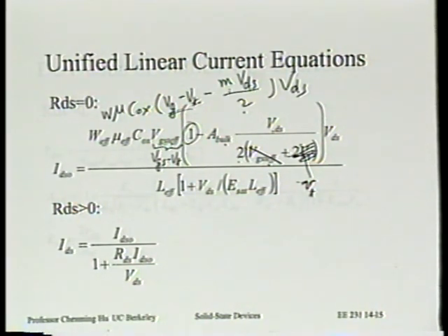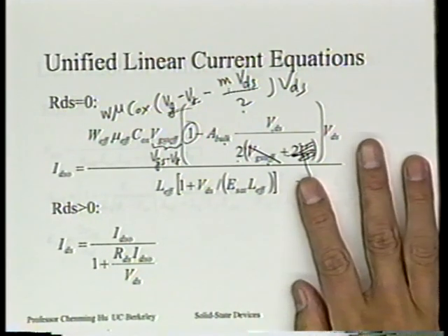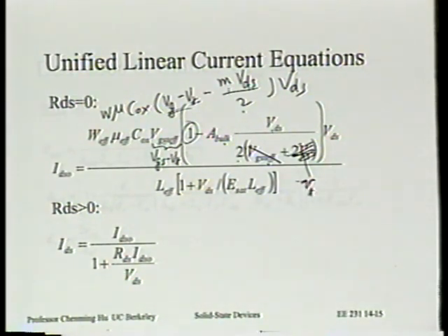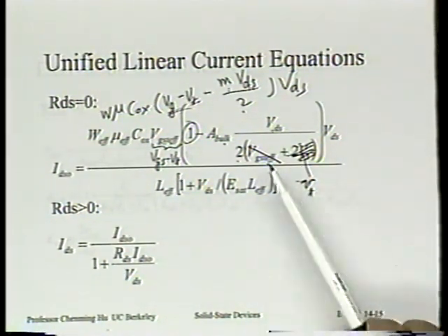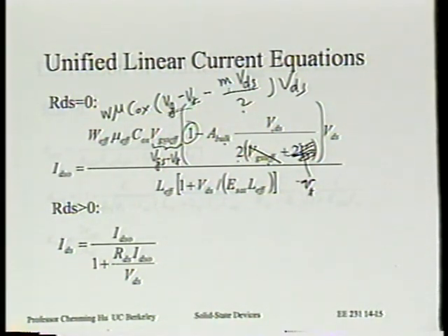All right? Okay. So because it's small, for our purpose today, in strong inversion, we can ignore that, right? Well, we are above VT, but we are not way above VT. We found out adding this thermal voltage actually makes this model better. All right? There's some justification for doing that. So this is what you want.